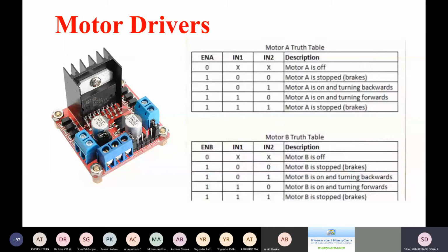So before going into that, as I said at the starting of the session, your Arduino board is only capable of working at low voltage levels, right? But if you are using a motor, a motor may take 10 amps, 15 amps, depending upon the torque and the load it is capable of taking, so it will take a heavy current. Then what are you going to do? Whenever you are going to use a motor along with the Arduino board, here you will get an important part that is known as a motor driver.